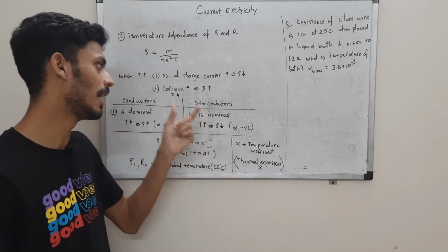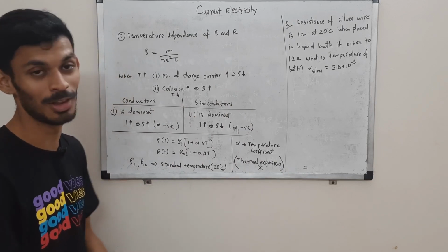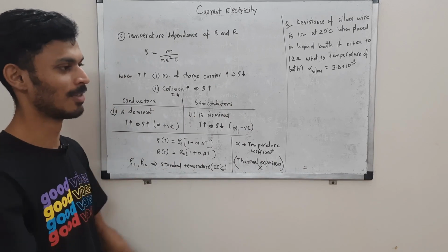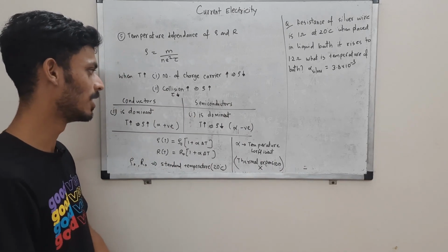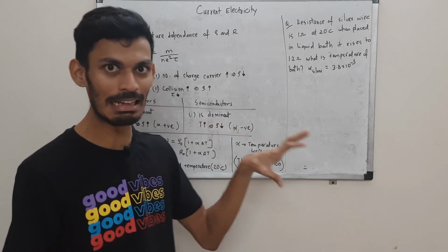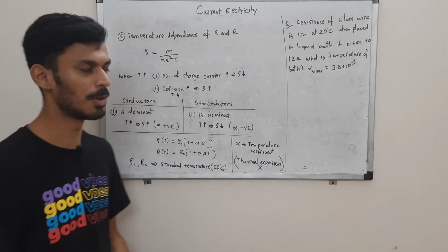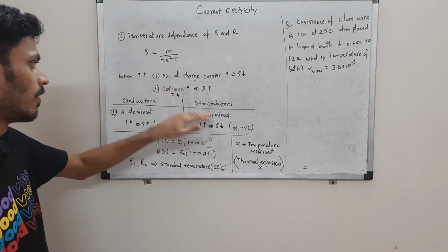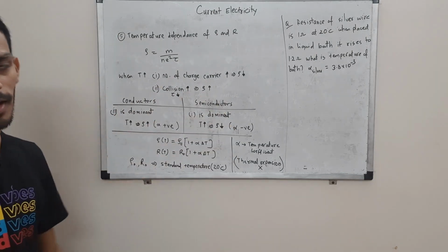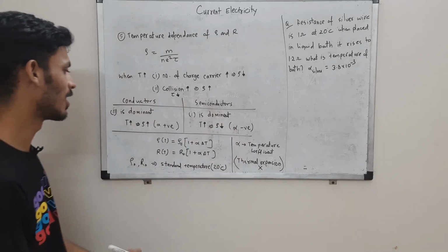We'll be studying them in depth. This makes them usable at higher temperatures, right? So they are used almost everywhere. What is that word? Ubiquitous. In every one of your electronic devices. So if you increase the temperature, your resistivity decreases, which is a good thing, right? So alpha is negative, we'll come to that. Here point 1 is dominant, there point 2 is dominant. For now you focus on conductors. When we come to semiconductors, you'll understand why it happens. Their charge carriers and working are completely separate.